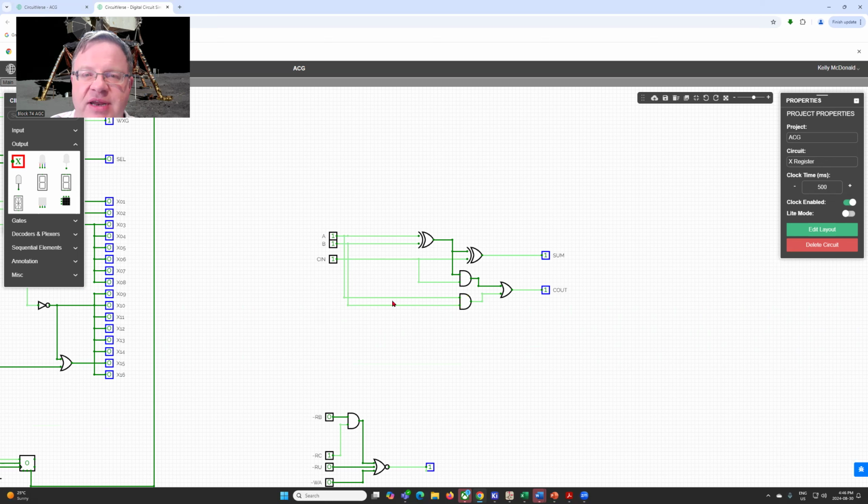Because what'll happen is if you have an adder, 8-bit, 16-bit, in modern processors 32 or 64, in order for you to actually complete your sum, the carry bit has to cascade through every single bit. The worst case scenario is where you have a binary number containing all ones, and then you add a 1 to it. A 1 plus a 1 means we have a 2, we've got a carry, which means you move over to the next position, 1 plus a 1, a 2, carry, and you carry every bit along the entire word size of your processor.